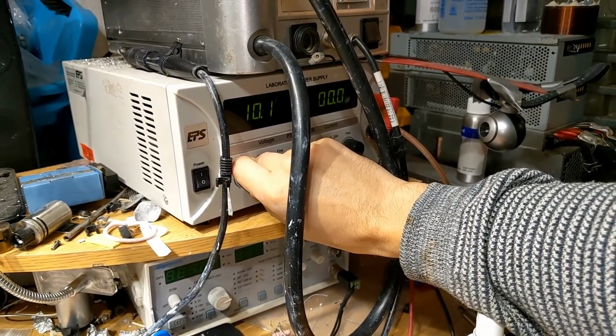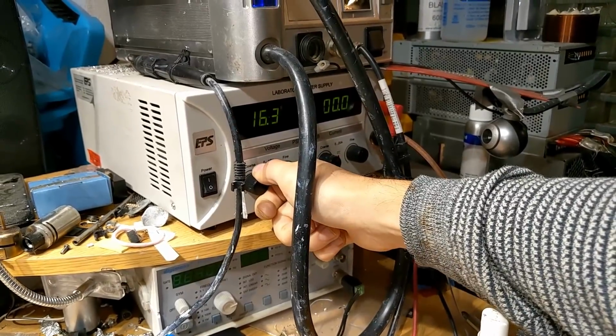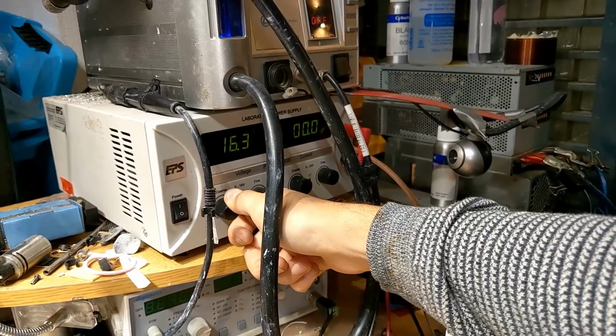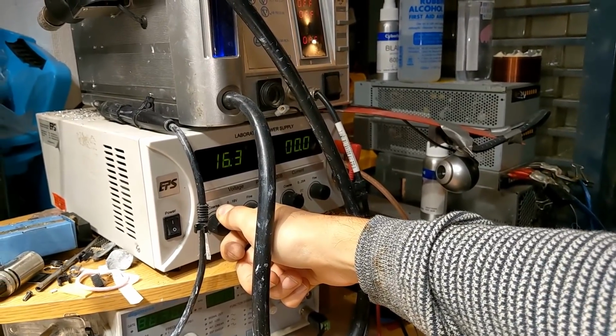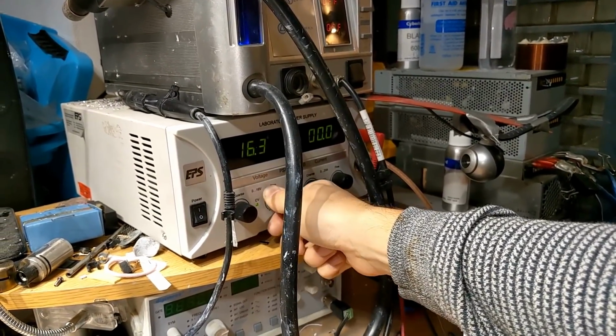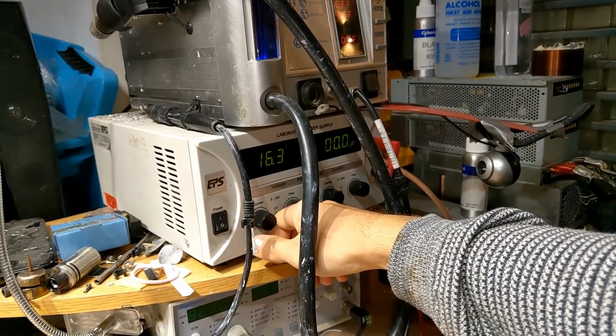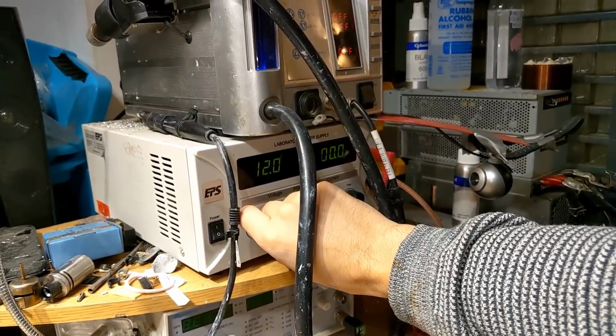So that has reconditioned this capacitor for only up to 16.3 volts. If the supply did allow me to go higher, then it would continue to draw current slowly and then taper off like it has. But considering this is going to be in a car only at 14 volts, 14.4 or 15 volts tops, that's absolutely fine for it.